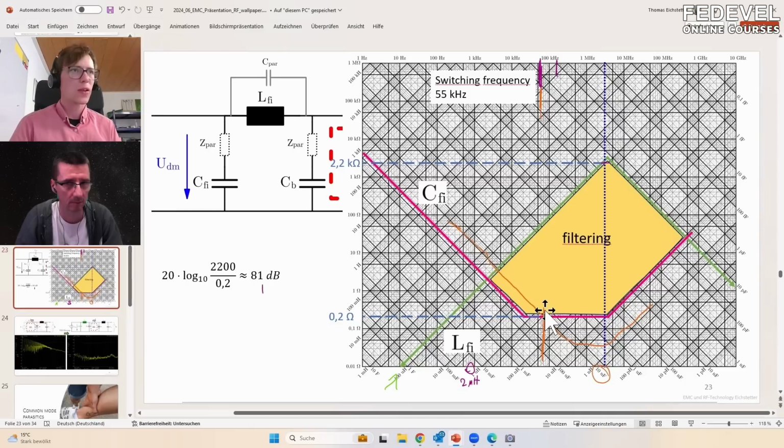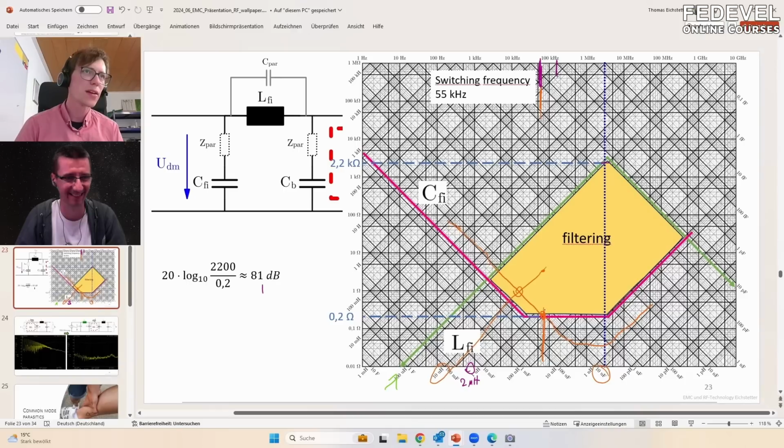And when you look at this frequency again, where we want to attenuate, let's say 20 dB, then we would use here a 10 microhenry inductor. That would be sufficient. Here is then the resonance frequency, which is still below. That's why we would like to use maybe two 10 microfarad, because then it would go not 2. That would not be enough. It would move only a little bit. When we have two of them, then your line is going down 20, here, and also going down here, and also here the inductance is a little smaller.